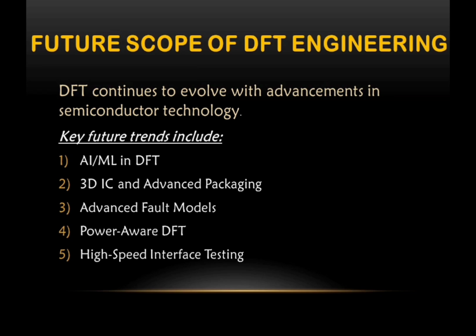DFT continues to evolve with advancements in semiconductor technology. The key future trends include AI and ML in DFT. Usage of AI helps generate test patterns and optimize and reduce test time. Machine learning aids in fault analysis and yield improvement. The next scope will be 3D IC and advanced packaging. Here DFT methodologies must adapt to chiplet-based architecture, and new testing strategies are required for heterogeneous integration.